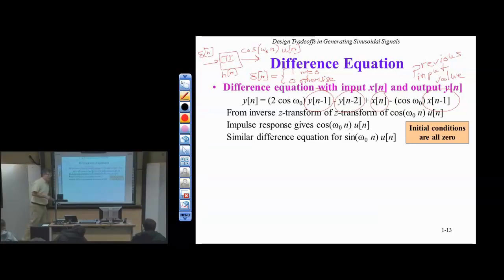It's on at n equals 0 and off otherwise. So that also is interesting because it tells us that in this case, x of n, the input, is nothing but the discrete time impulse. So most of the time it's 0 actually. It's only 1 when n is 0. Do you just assume that the input is a delta function?